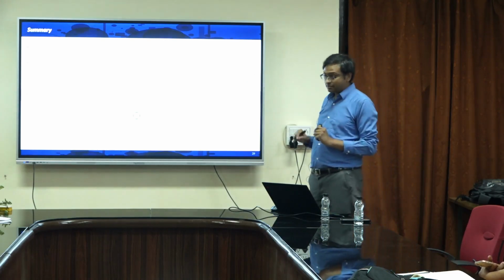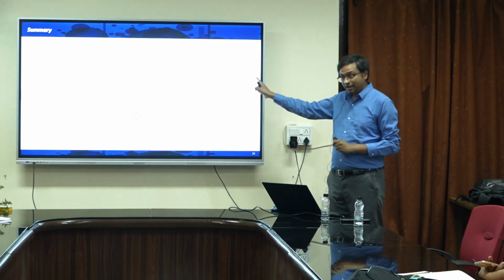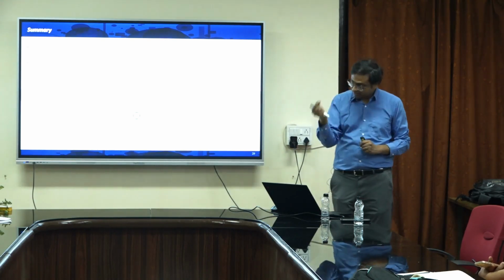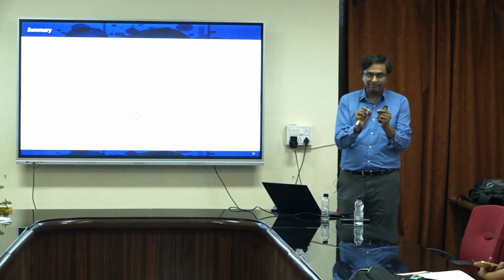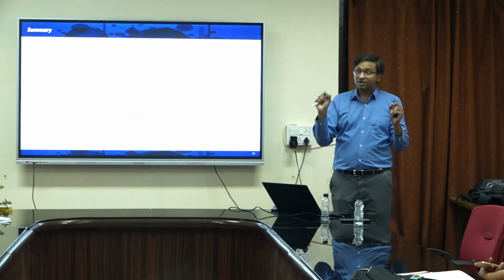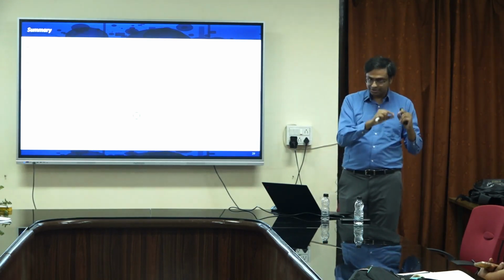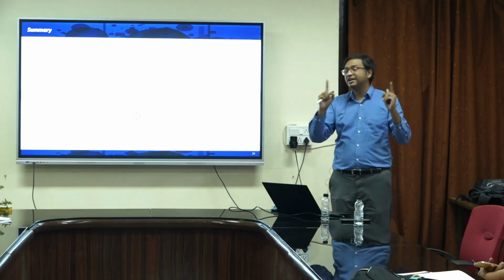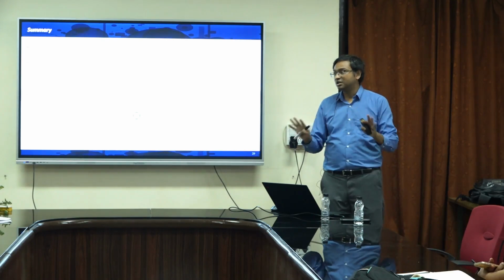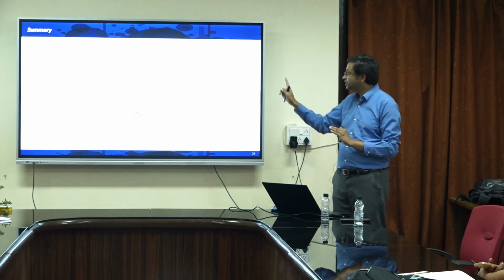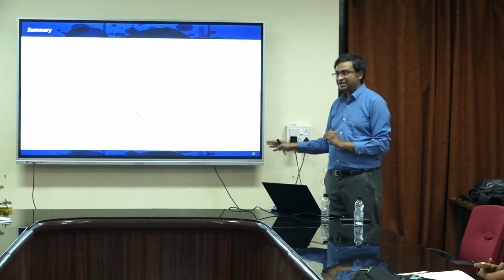But palladium and platinum are promising contacts with degenerately doped channels. Not only high work function metal, because for MoS2 we found that only low work function metal does the trick. For P-type, we need both a high work function metal to reduce the Schottky barrier, and then degenerate doping to reduce the Schottky barrier width. For MoS2, we did not need that. So for WSe2, we need both. That's why doping becomes even more critical for P-type materials.